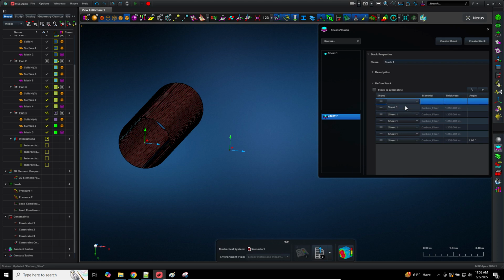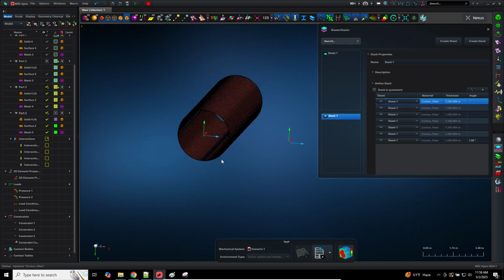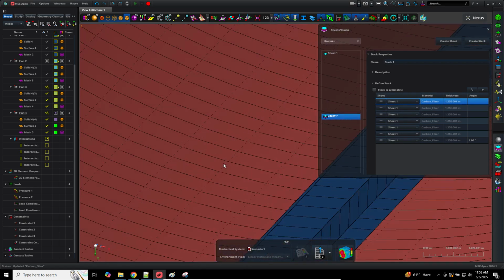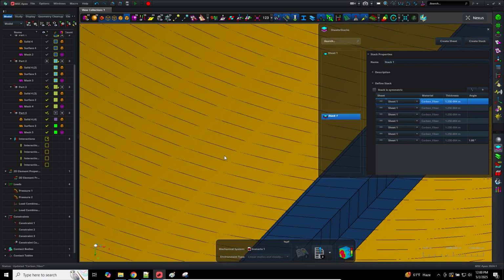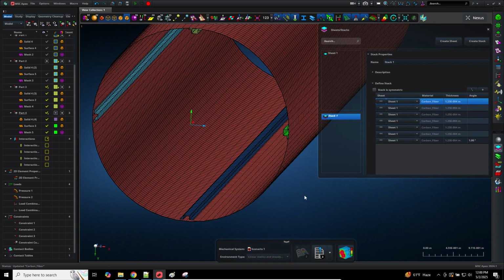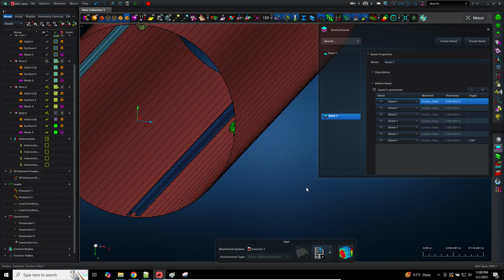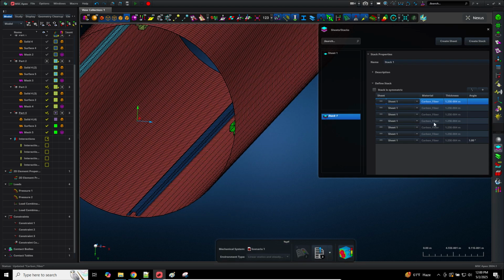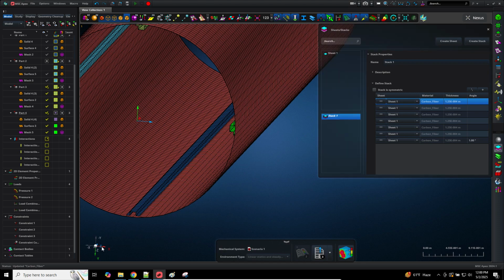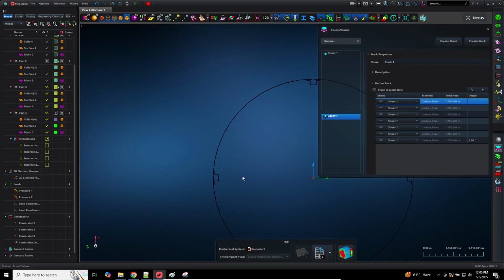If your thickness is too small, you will get a lot of errors when it comes to the glue contact. So when you have the attachments here with permanent glue, when I tried this example, if I used only 4 layers, the thickness of these sections was too small and there were issues detecting the contact.